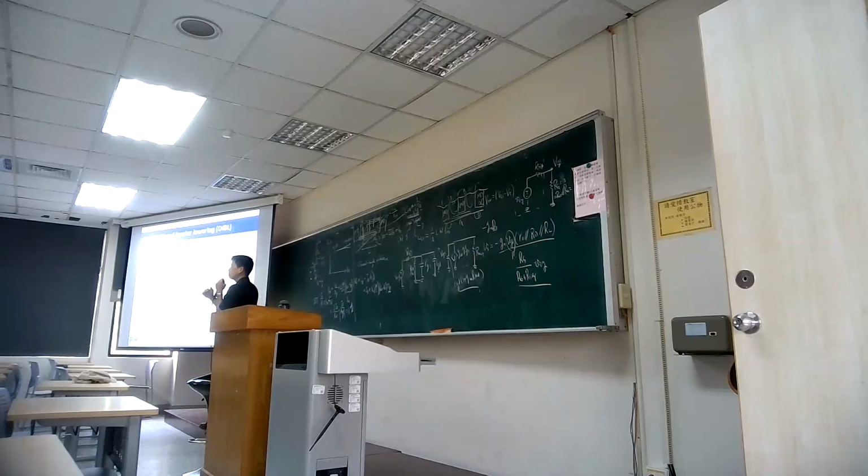Okay. And also that will cause threshold voltage reduction, because initially we get certain drain-induced barrier lowering. Originally we judge the threshold voltage based on the metal-oxide-semiconductor process, but during that process we assume it is a bulk material with a really long channel. But once your channel is short and you apply a voltage on the drain side, you lower the boundary between the source and drain, and then maybe that will give you certain leakage current.